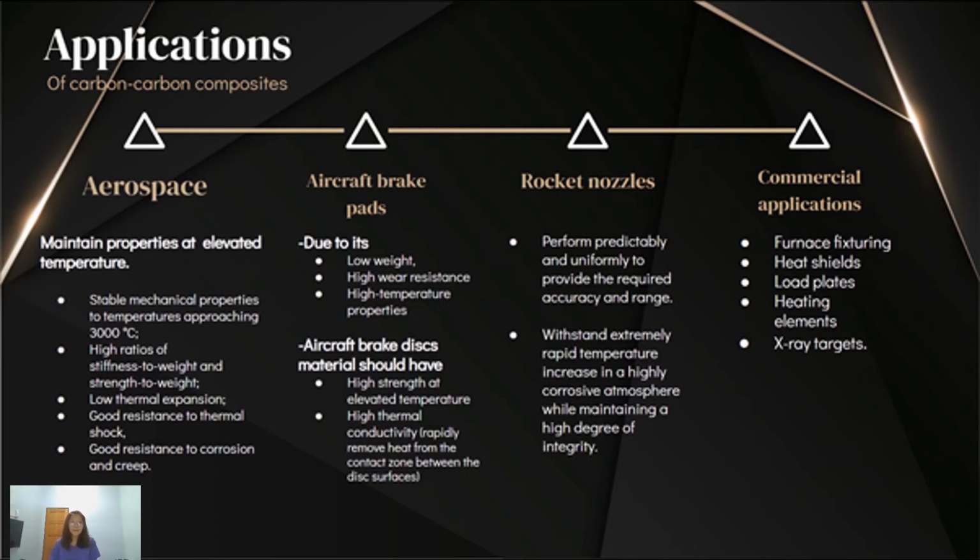Next, carbon-carbon composite can be used for rocket nozzle production. Materials for nozzles should be able to perform uniformly to provide the required accuracy and range. It also needs to withstand an extremely rapid temperature increase in highly corrosive atmospheres while maintaining a high degree of integrity. For commercial application, carbon-carbon composite can be used in furnace fixturing, heat shields, load plates, heating elements, and